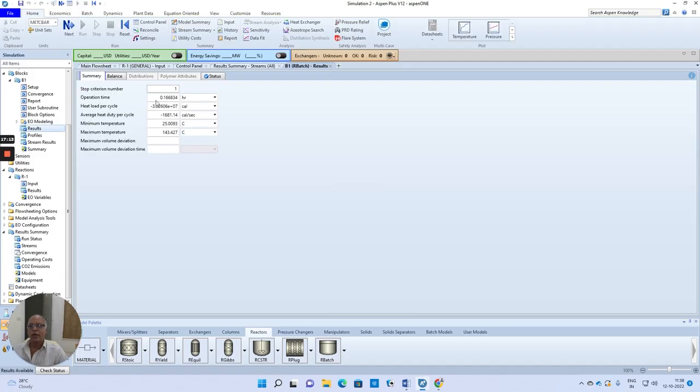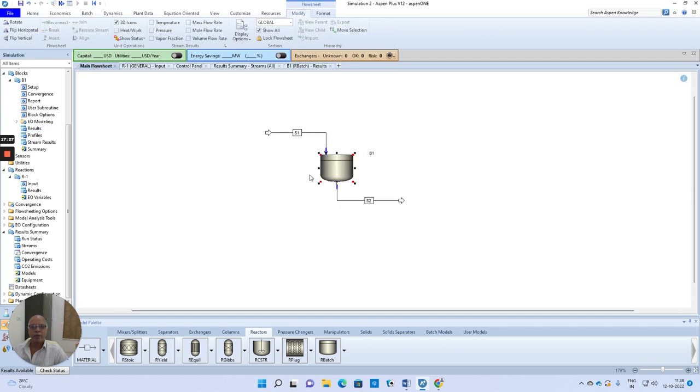So you can see, in order to reach this 90% conversion, operating the reactor at 25 degrees centigrade, we require about 0.166 hours of time, about 10 minutes. Of course, in this case, it may be quite easy for you to check what time may be required to solve the problem. You know, it is minus ln(1 minus xA) is equal to kt. xA is known, k is known. You try to calculate the time analytically and compare it with the simulation result.